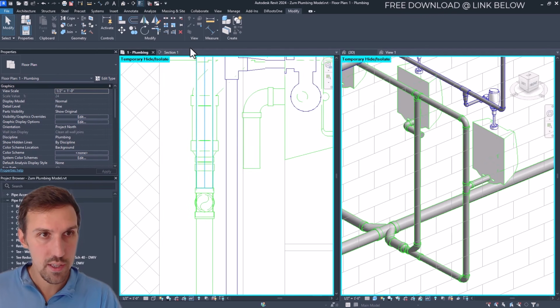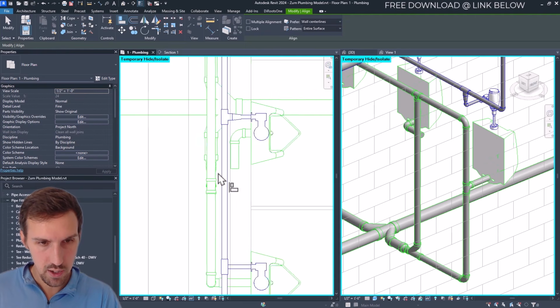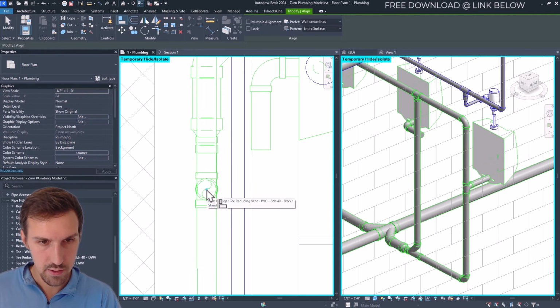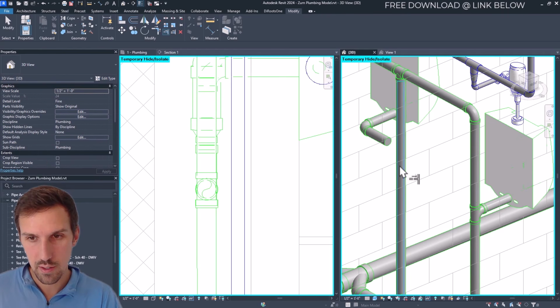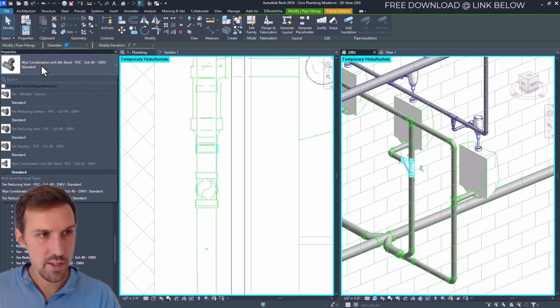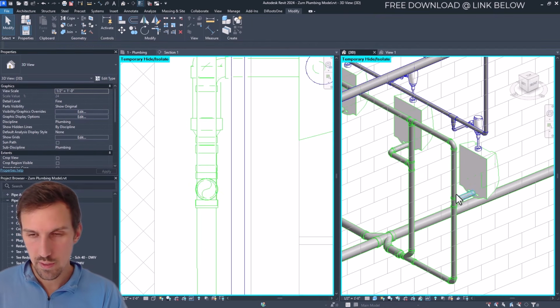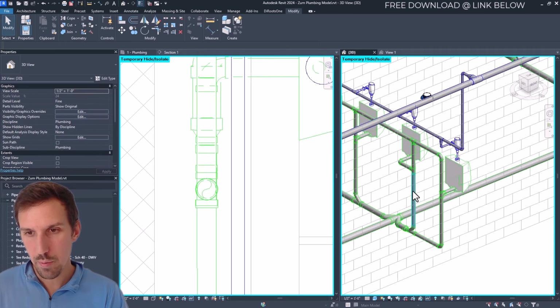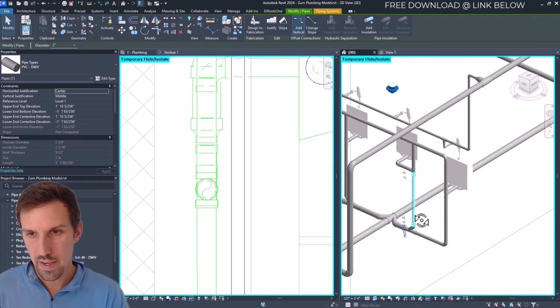So unfortunately, Revit, when we hit the align tool, it doesn't, oh, it does. So we can click on this guy right here to the midpoint, and then we can click here. Look at that. And then hopefully we just use our trim extend single element, click, click, and would you look at that? We could change this to a sanitary T reducer. Let's see, T reducing, that looks good. And now we pretty much have everything plumbed up, looking very nicely.